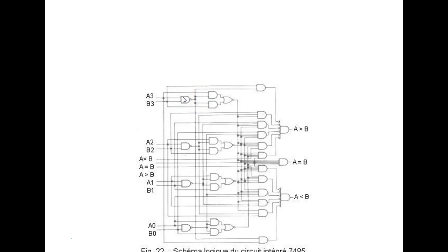So what we do is we take that transistor circuit and represent it with a what? With a symbol. So as soon as I represent it with a symbol, I don't really need to know what's inside the gate. All I need to know is what the gate does. Right? So this gate right here says all highs to get a low. Then we get into combinational logic circuits, which are made of all these gates.